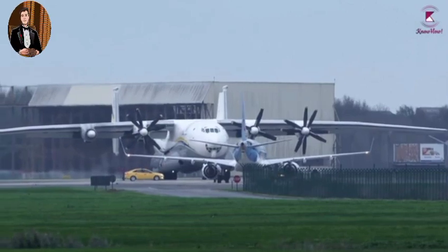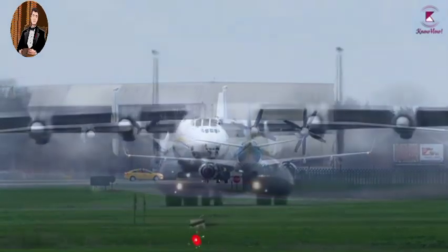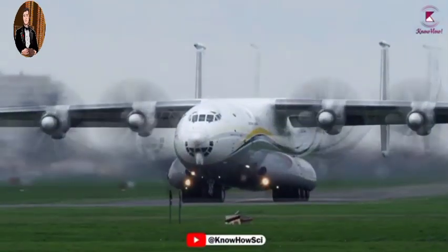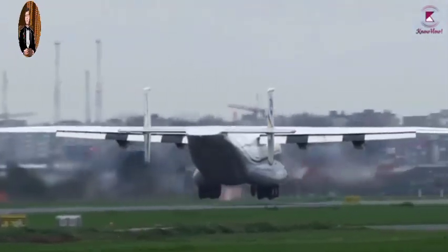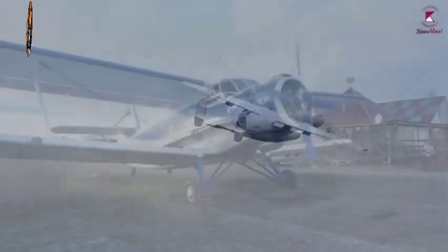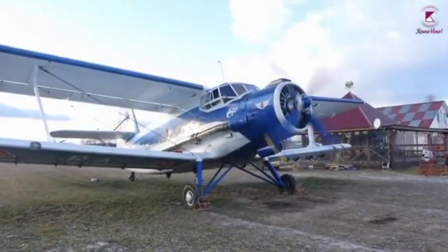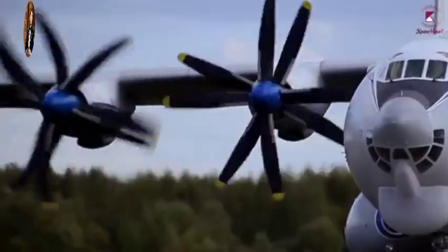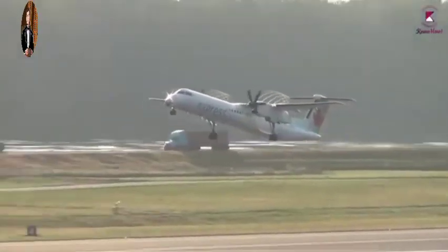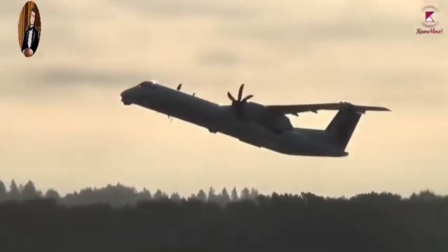A turboprop engine is a variant of a jet engine that has been optimized to drive a propeller. Turboprop-equipped aircraft are very efficient at lower flight speeds, less than Mach number 0.6, burning less fuel per seat mile, and requiring significantly less runway for takeoff and landing than a turbojet or turbofan-powered aircraft of the same size.